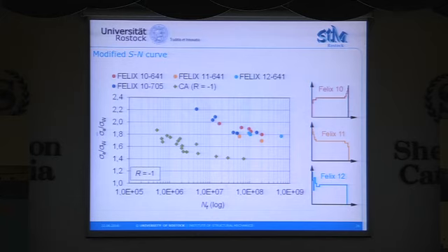First, I would like to show you the results for Felix, and because we have problems reconstructing the sequence, we have performed very simple reconstruction types at first. We have used the smallest amplitude at first and ended with the highest, and vice versa, and we have a mixture. And moreover, we have different values of the maximum amplitude for the Felix 10 spectrum, with 641 megapascals and 705 megapascals.